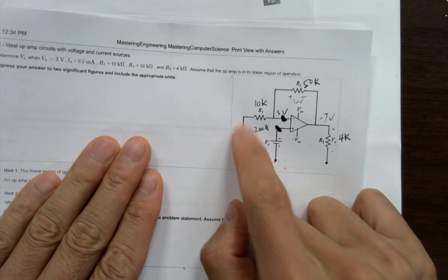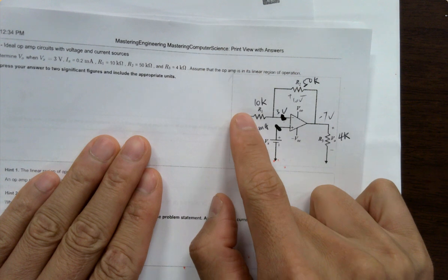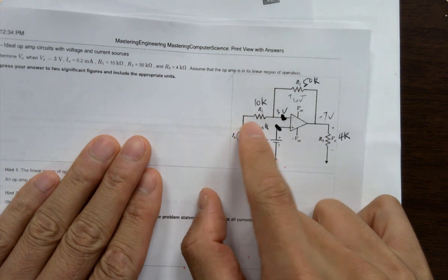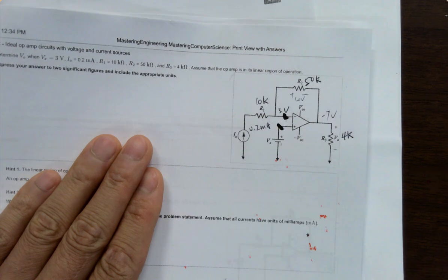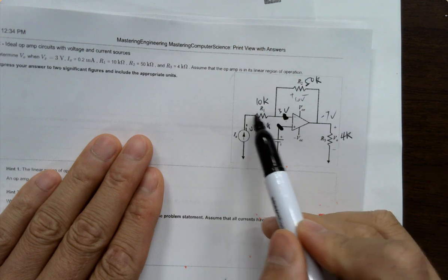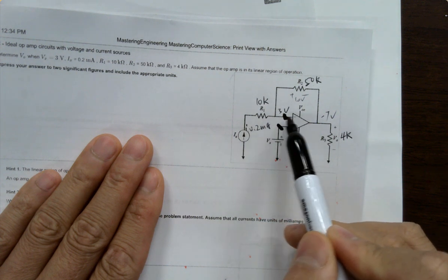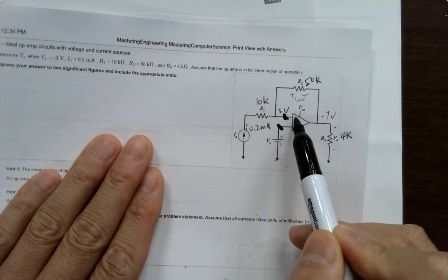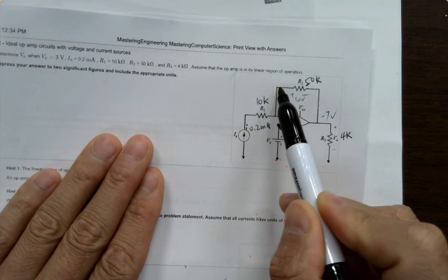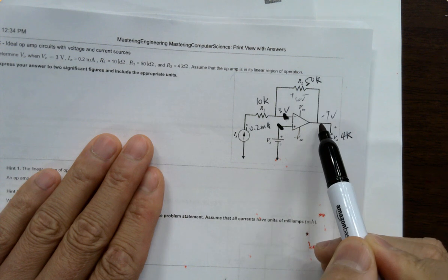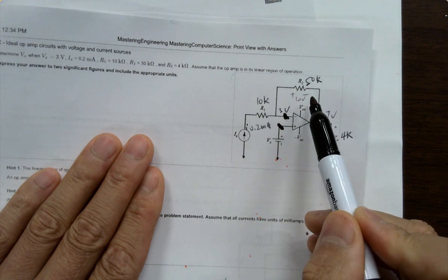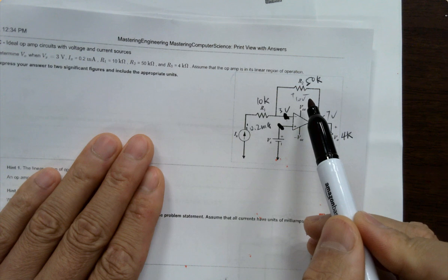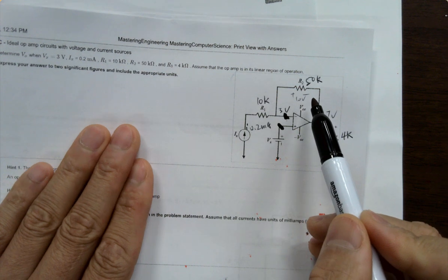This one is a current source. Now this time it's different. It's not a voltage source, so we'll have to use the voltage minus this voltage to get a current, because the current is provided. It's even easier. So current comes in. Does it go here? No. Super high input impedance means a disconnected circuit, so it's going to go up and reach here. You got a current, you got a resistor. It's super simple to calculate currents or voltages if needed.